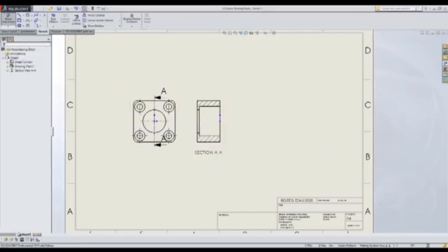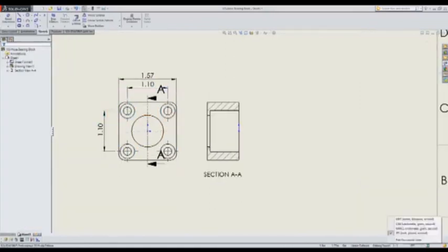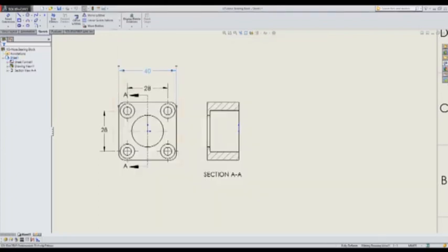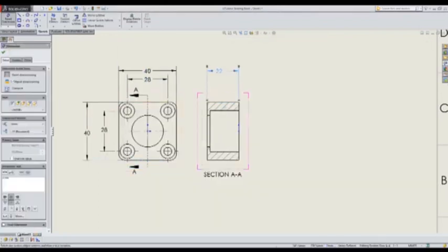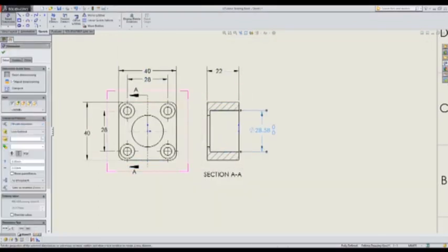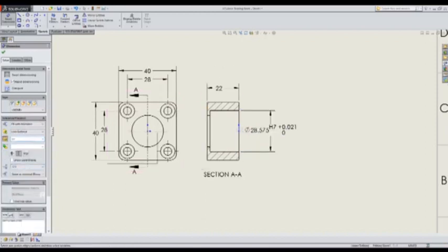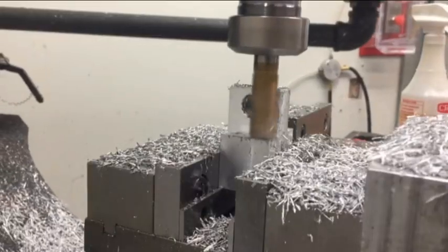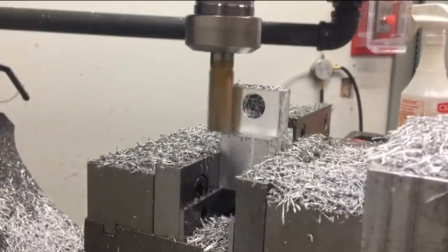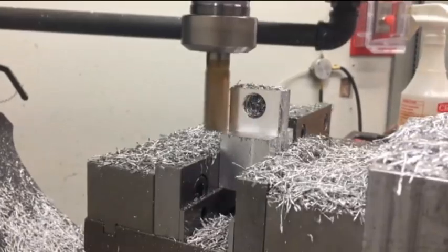So, knowing the different tolerance zones and having a list of a dozen or so preferred fits, we should be able to design parts that fit together how we want. We also have a means of vaguely checking if a manufacturing method will be capable of hitting those tolerances. In addition to the oft-used pin and hole example, the system can be used for internal and external parallel faces, such as keys and keyways, or other features of size.